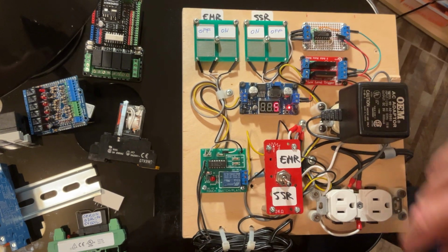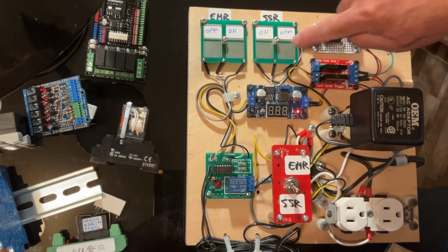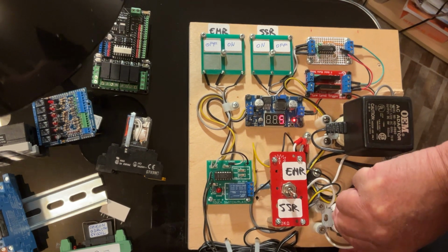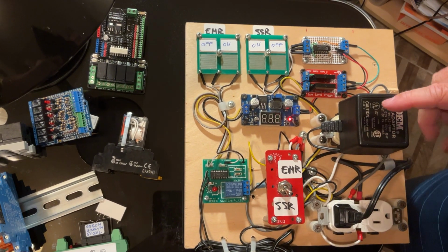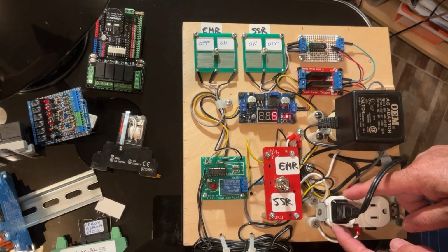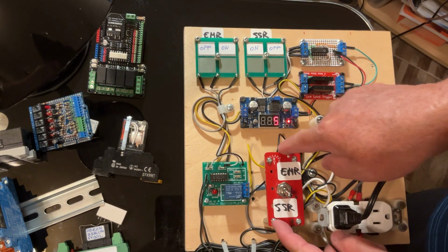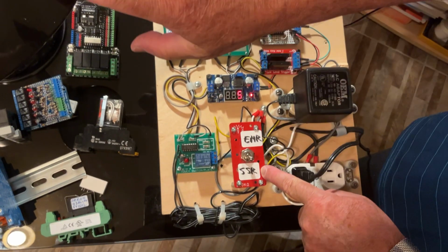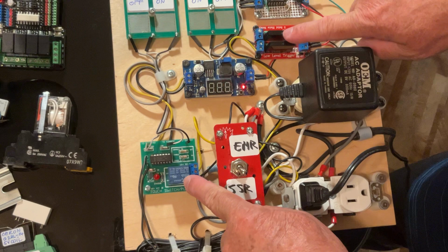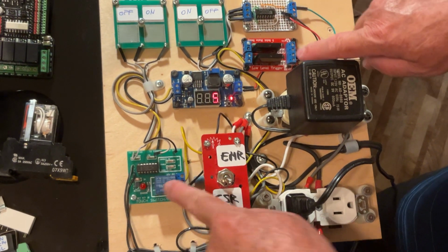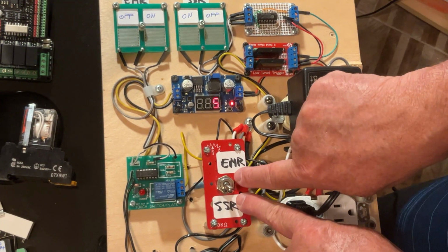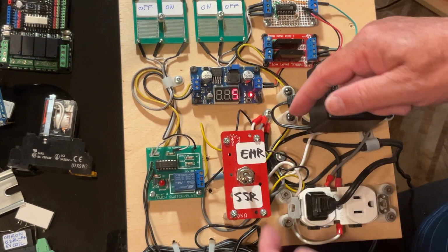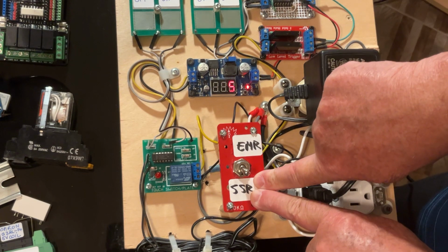I'm going to pick up my load and connect it here. The last element I should talk about is this one here in red. This contains a power switch. I have only one load, but I have 2 blocks of relays, electromagnetic and solid state. So I use this power switch to connect my load over each group one at a time. So now it's connected over the solid state relay.